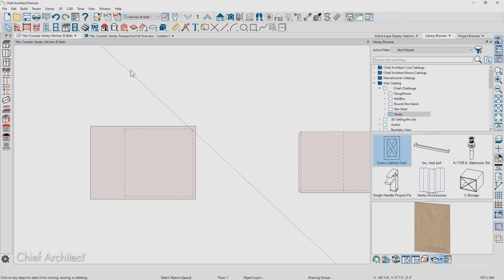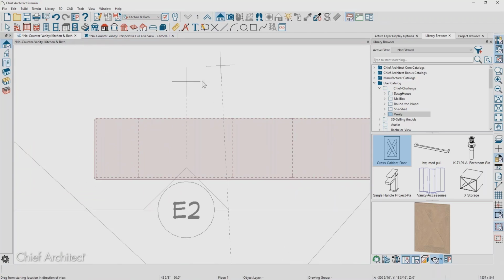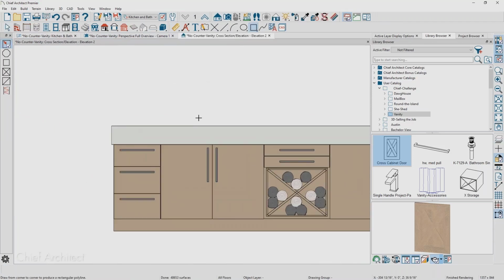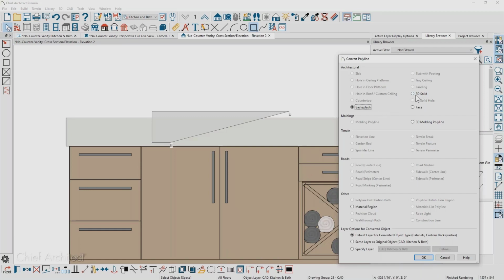And when I actually did that, when you shoot your elevation, I used just a CAD box. So using the CAD box tool, come in here and you click and drag the box, and then I just shaped it. Using the break tool, which is either in the lower edit menu or number 3 on your keyboard, I put a break in here, and then I just pulled that up and snapped that into place. So once you have the shape, I converted that into a 3D solid. So that process, we come down and we convert that into a 3D solid.